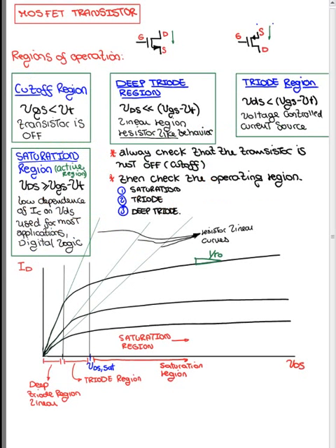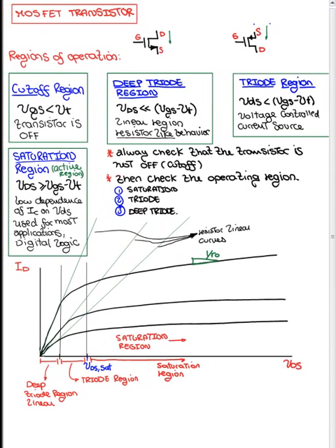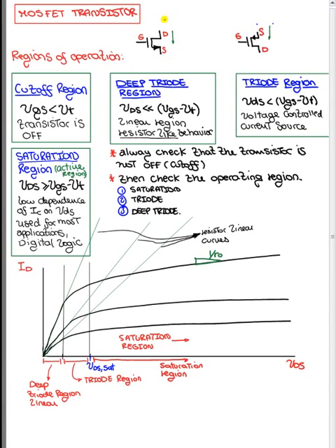Alright, so here I leave you with a review sheet. So this is just the representation for an N MOSFET. Then we have a P MOSFET, right? And then the regions of operation, remember the cutoff region, or in this case the sub-threshold region, is when the gate to source voltage is less than VT. It means the transistor is completely off, right? There is some very little current.